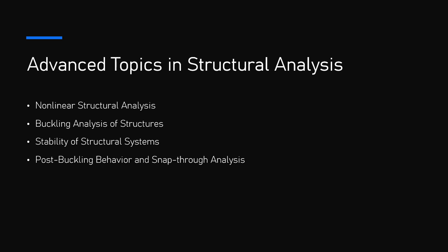3. Bifurcation and snap-through. The bifurcation point is where the system transitions from one stable configuration to another. For snap-through analysis, bifurcation theory is used to identify when the system will switch between different equilibrium states under load changes. In snap-through analysis, engineers look for regions in the load deflection curve where there is a jump or sudden transition, indicating the occurrence of snap-through instability.